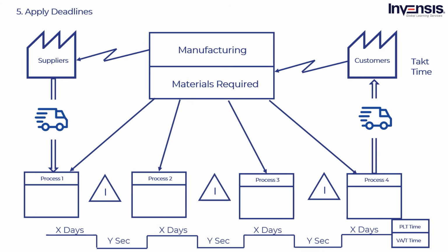And after calculating, there comes an end to the process. After completing, it's time to put it into action. Check if a process is taking a huge time or if it has more non-value elements. Then, cut waste and track efficiency. Then, alter the process and map accordingly where you can find the least waste. Simply put, it means update your VSM as needed so it accurately reflects your current processes.